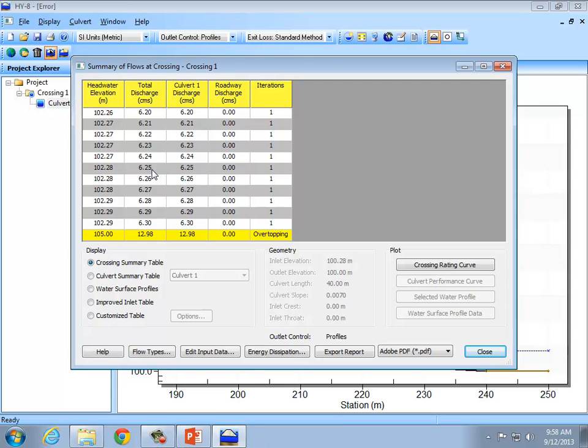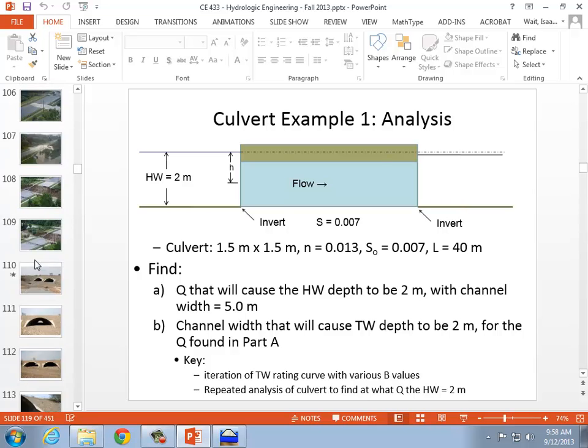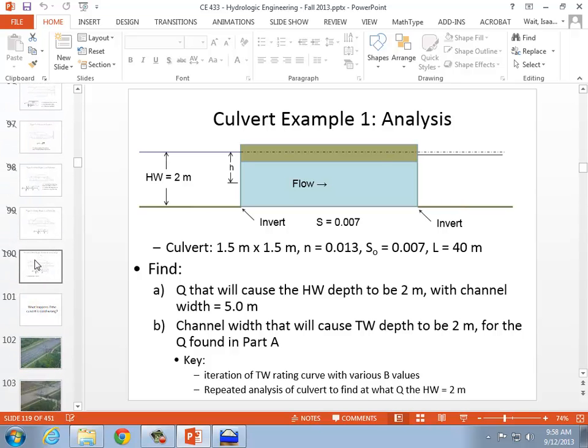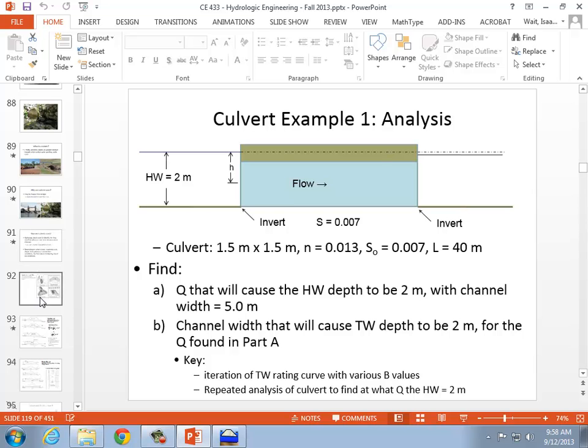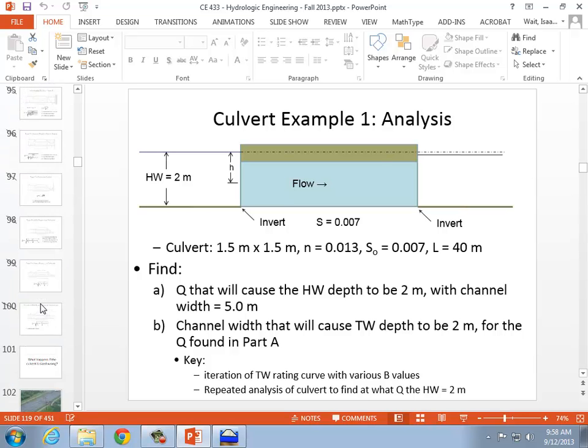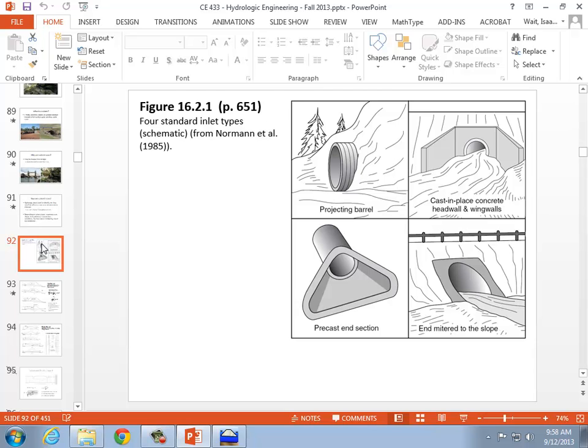Any questions? Yeah. So, what exactly does that do? Is it kind of like the orifice thing, like it reduces the energy loss or something? All right. Good question. In this case, it must not be just strictly, let's first look at this figure. And so it's some sort of a transition that's guiding the flow. I guess it's more like this. So instead of just being a pipe sticking out of a hill, these wing walls guide the flow.